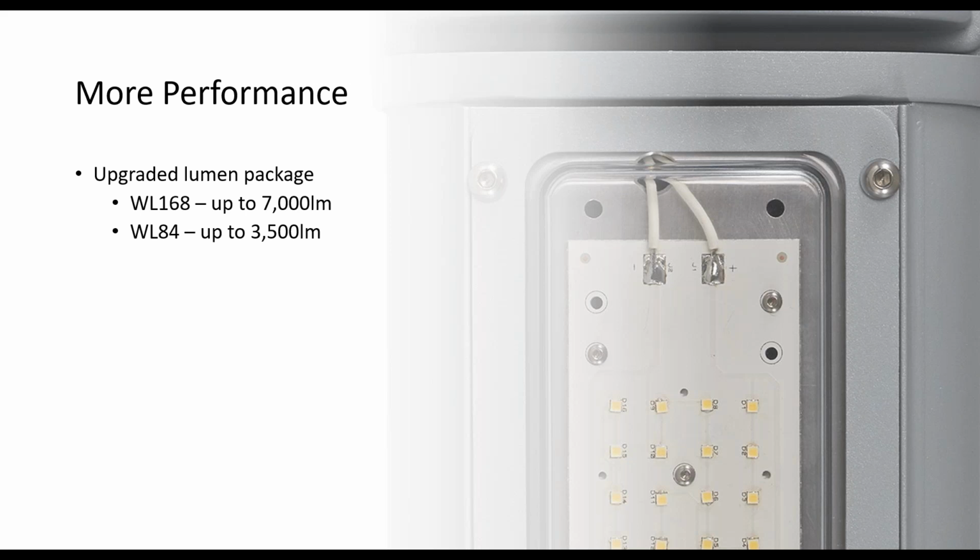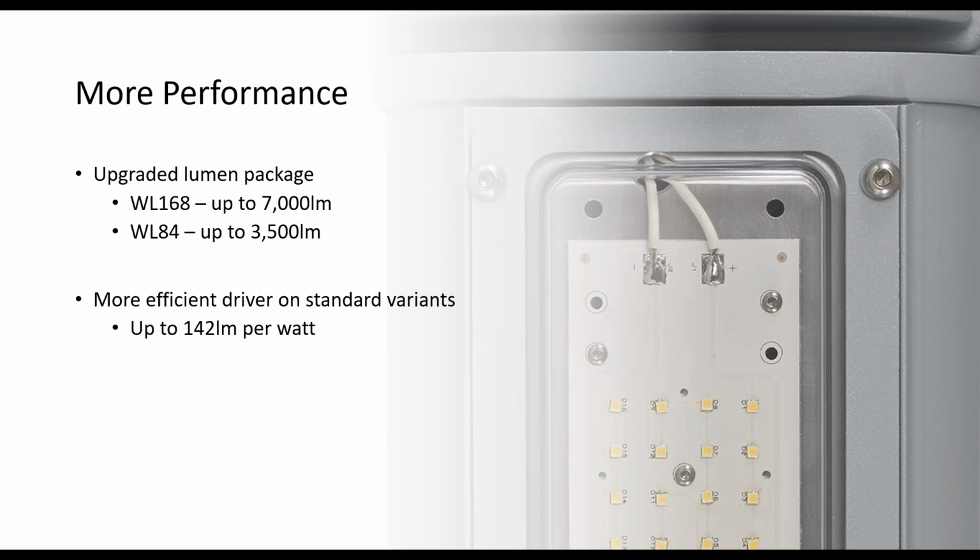And as well as providing those products with more power, we also wanted to make them more efficient as well. So the new linear is fitted with a brand new driver. That means efficacy has been improved to 142 lumens per watt based on the Zone 2 variant, and 133 lumens per watt on the Zone 1. So these are figures which we consider to be industry leading. And just before I move on, just to mention that the driver upgrade applies to standard variants only, but there will be upgrades to come on the emergency versions in the coming months, so you can watch out for those ones coming through.